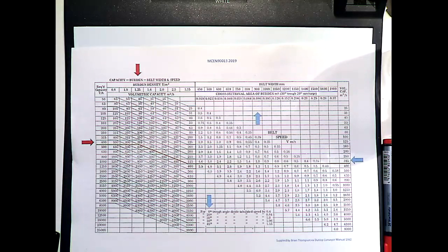These two here, I think they're pretty much the same as the first one, but if you want to, if somebody gets bored, you can time it, and you find out that the funnel flow actually empties faster. The funnel flow is good because it doesn't have material sliding down the outside. This one here, the mass flow, the material does scrape and scour, but there are some reasons why one might be chosen above the other, okay? Now, we're really getting into the area where we're going to start looking at conveyors and some of the friction and powers.